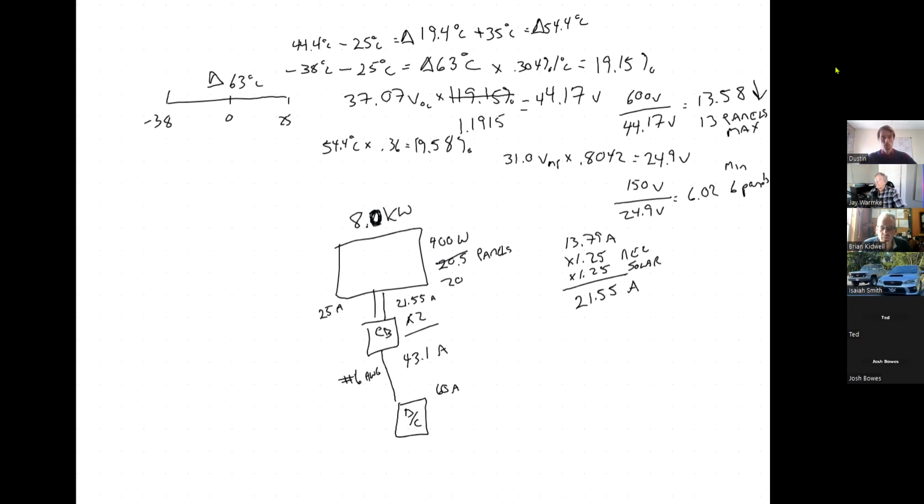It has to be below 60, right? Yeah, it's got to be below 55, because the 6 gauge is rated for 55 amps, and you're really protecting the wire. This is only rated to 55 amps. So you round up to the next available size.